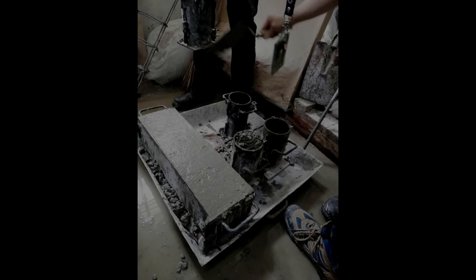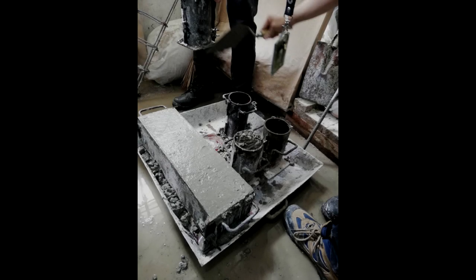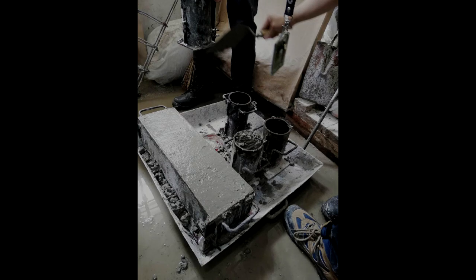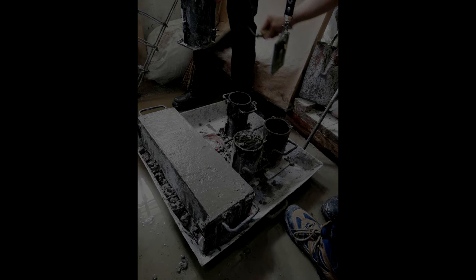Some of the applications of making specimens include in situ curing of columns, beams, or slabs by spraying curing compounds or by wet burlaps. Another is curing of specimens of the actual structure to ensure strength capacities. Molding and curing is typically done on slabs on ground like pavements, sidewalks, parking spaces, driveways, floors, and canal linings. Also on structural concretes like bridge decks, piers, columns, small footings, and retaining walls.